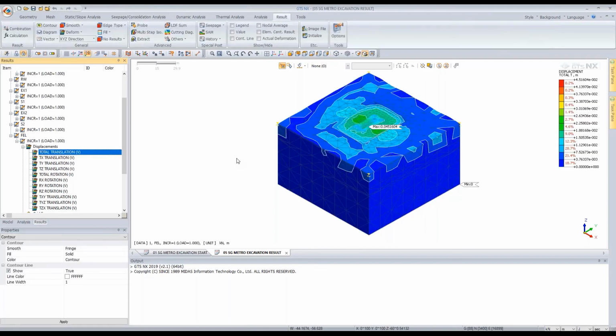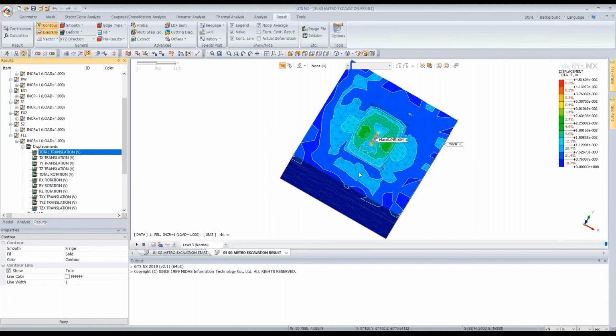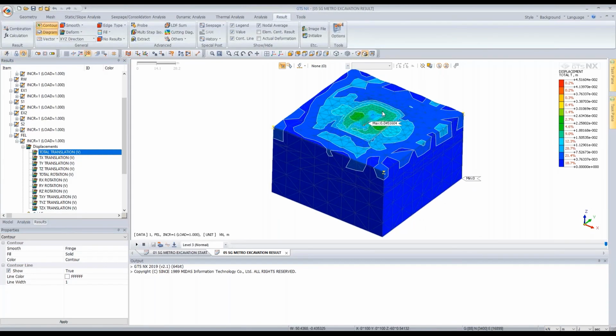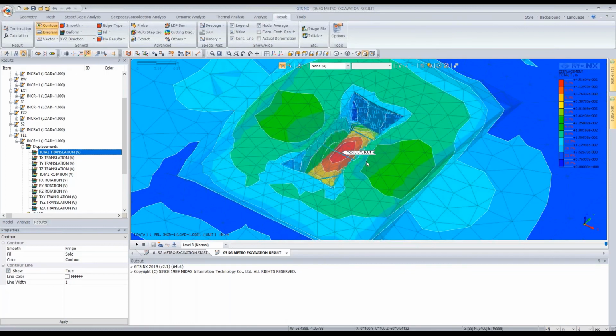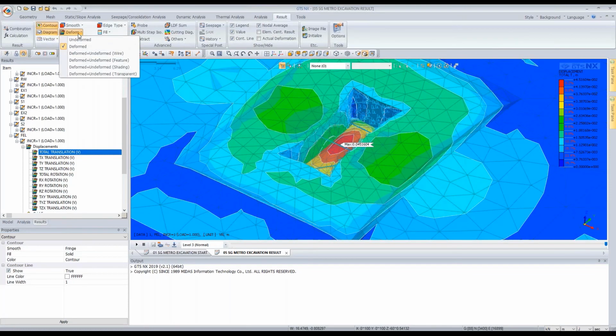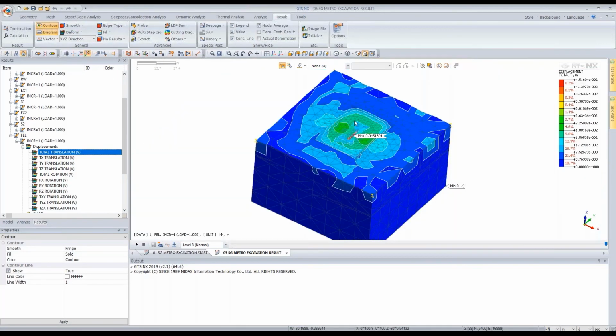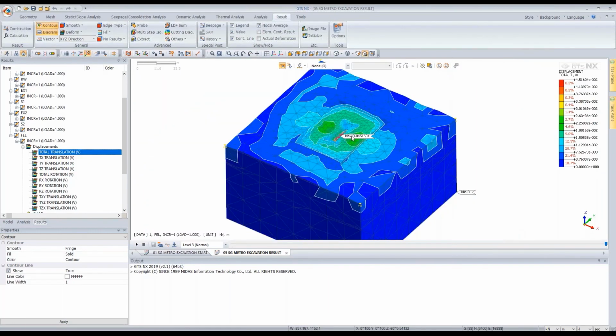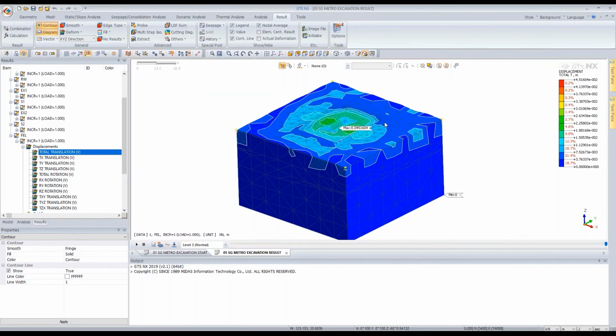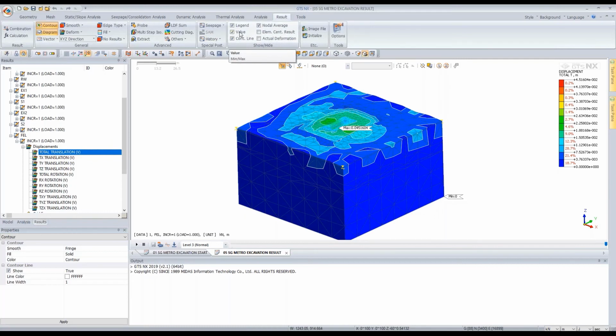This is the total displacement, as you can see here. And you can control the deformed or undeformed under here. Undeformed and deformed. And you can see the maximum and minimum values directly under this window. Check this values function and unselect, select, like this.